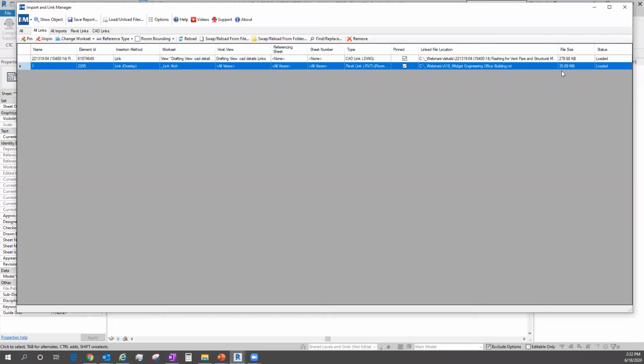It also has the file size embedded, which is kind of nice. If I saw a CAD file that was 40 megabytes instead of kilobytes, maybe it's a giant equipment file in an industrial plant or something like that, where all the industrial equipment is based on 3D CAD files, and it's got every nut and bolt and washer and everything on this giant piece of assembly. A lot of times those files can get really large, but they really slow down Revit because Revit really doesn't like those large CAD files.